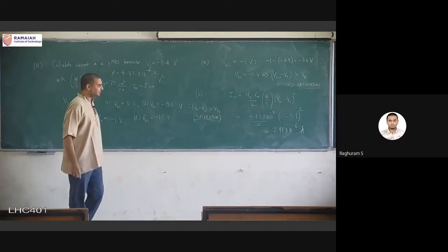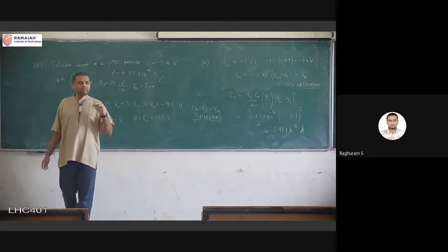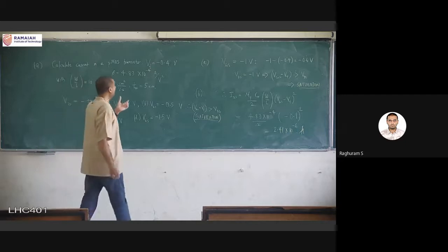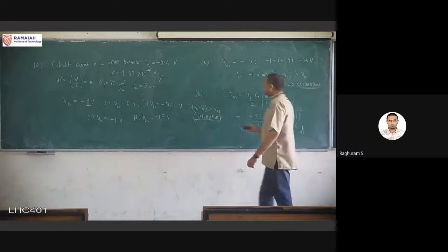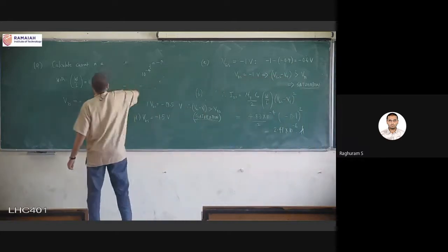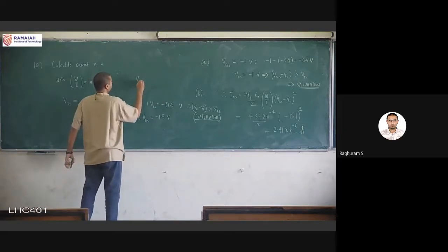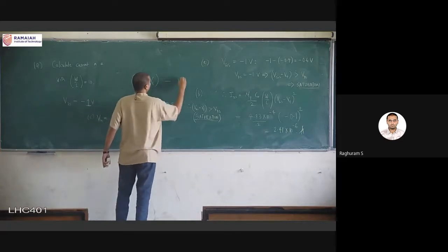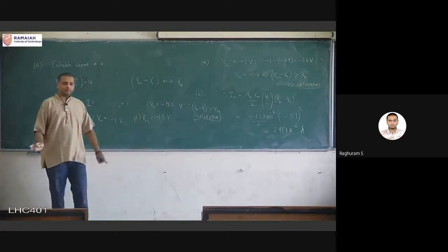The second thing is, once you have found out whether it is on or off, if it is on, then definitely you have linear and saturation. You have two more regions. You have to find out which is the region. And the main equation, always what we will compare is VGS minus VT and VDS. Always we will compare this only, Nmos or Pmos, doesn't matter.